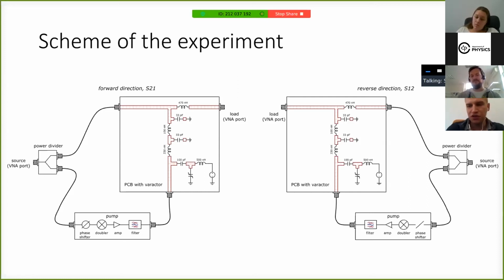It may be just interesting to look at how physically these kinds of circuits are done in the literature for microwave amplifiers or low frequency amplifiers. How do they visually look? Maybe they are soldered and locked in a special metal case or something like this. So do people take any special measures to protect it? Well, at this low frequency, it definitely shouldn't be an issue. At 100 megahertz, I think the parasitic coupling would be very, very small. Okay, but that's something we need to check for the next step when we try to move to the higher frequencies.